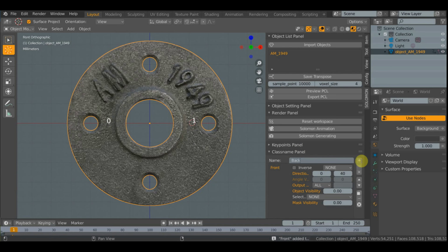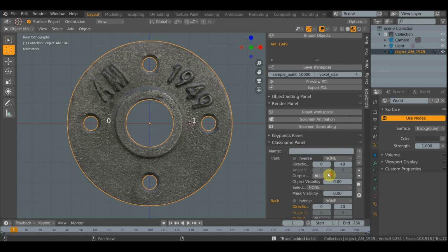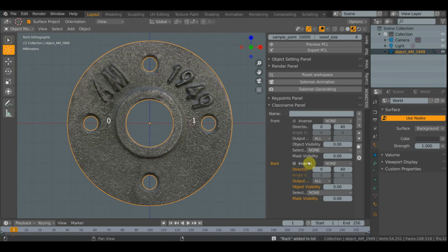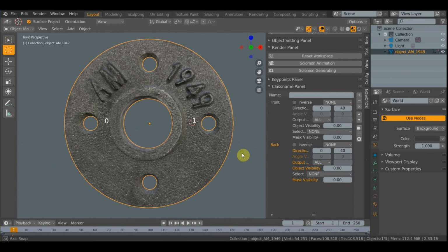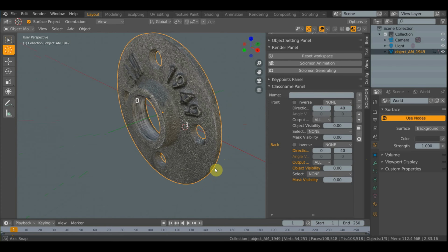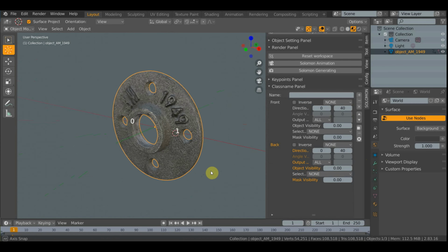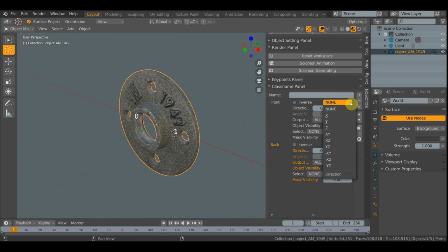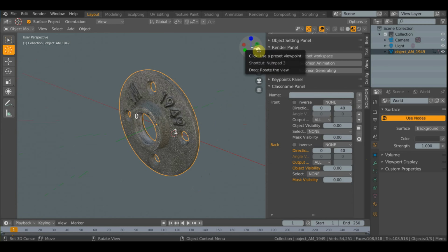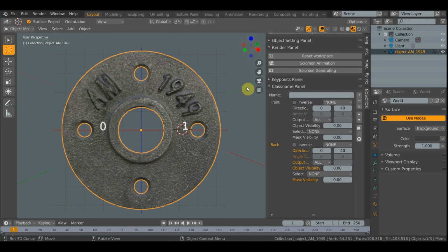The subsequent part is one of the most important to put the annotation into the correct place. To understand it in a better way, I'm going to rotate the object a little bit to have a better view for each direction of the workspace in contrast with the object. If I open this list, you will see 19 possible points of view. Each point of view starts from the camera to the origin of the object. You can see the 3 main principal arrows, where X is red, Z is blue, and Y is green. All these 3 vectors are positive axes starting from the origin.